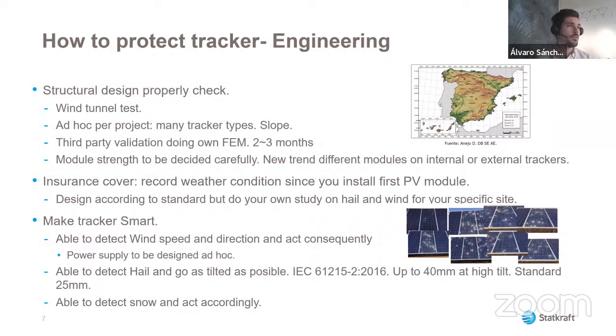To do all of that, we don't do it in-house because we don't have enough resources, but we always do a third-party validation. We have a short list of companies; there are 3 companies on the market that we have validated to do this check. It's also important to mention that this is not just a review of the calculations done by the tracker supplier. It is a validation done totally by them. They basically build the model, they build the tracker, and they check everything. They redo the structural calculations with the inputs from the tracker supplier, and they also check the inputs from the wind tunnel test and the design of the tracker.